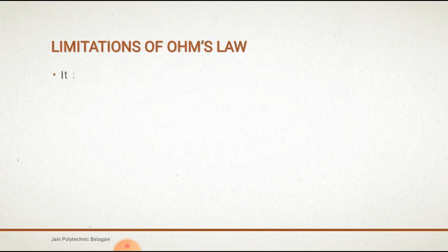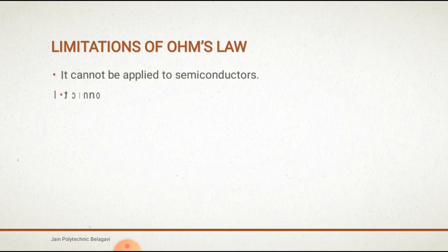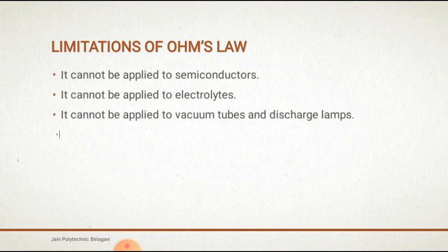Limitations of Ohm's law. It cannot be applied to semiconductors. It cannot be applied to electrolytes. It cannot be applied to vacuum tubes and discharge lamps. It holds good only at constant temperature. It cannot be applied to complicated circuits having a large number of branches and EMF sources.